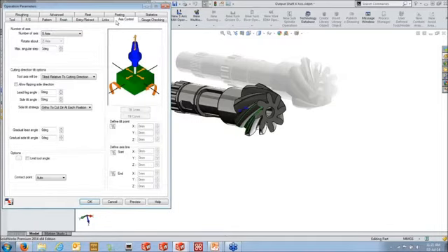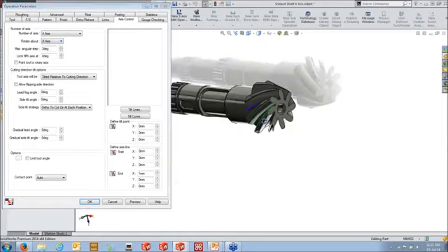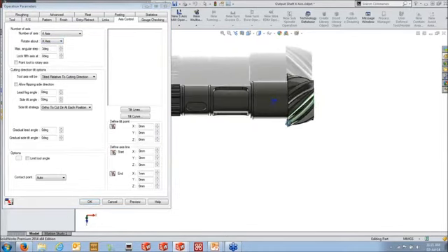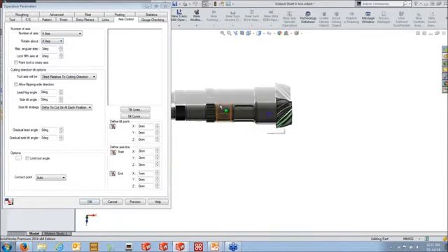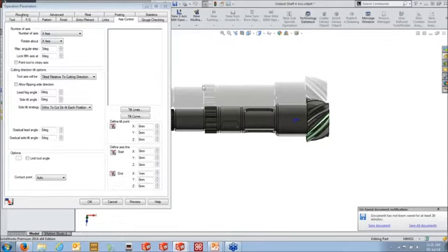We'll also go in and set our axis control. So this is where we really define how many axes we're using. In this case, we'll use a 4th axis. And we need to tell it in here which is the rotary axis as well. So we need to go in and say this is our rotary about our X. If we're setting this up parallel to the X direction on our table, that's where our typical rotary axis might be. This is where we'd go and define that.